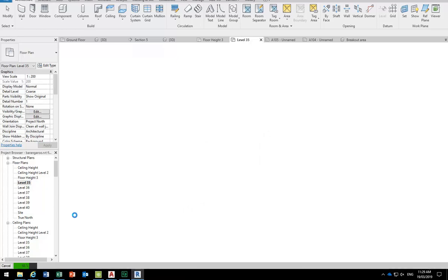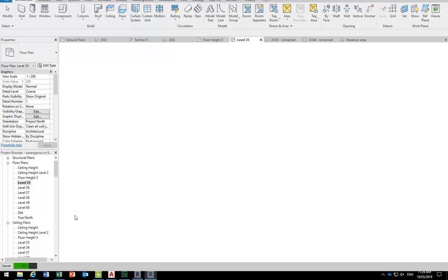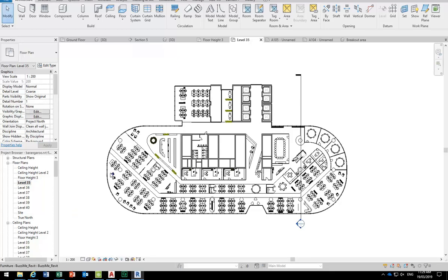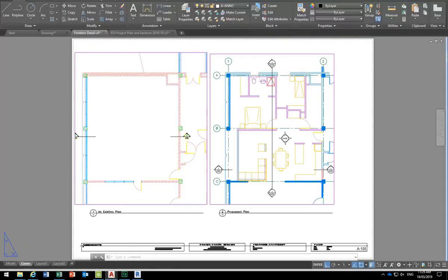Yeah, binding. So is this binding XREF? Oh, no. Okay, yeah. Because when you've got an XREF, say you forgot to turn that option off and you've done some work in the AutoCAD file, you can bind them afterwards. So there's a bind option for external references, which we might look at as well. But for now, I'll just go back into AutoCAD.